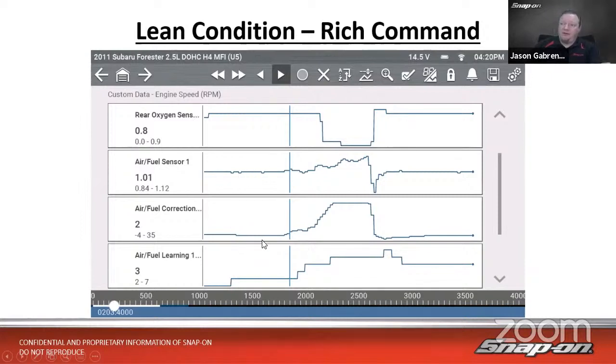So here we are right at the very beginning of the vacuum leak. We see it's fairly stable leading up to it, with very, very few changes in the signal. Rear's pretty flat. This is at idle, by the way. And then we see we're at like a 3% long-term fuel trim. All right, so as we open it up, we see that the fuel trim goes up. This is the front short-term fuel trim. We see the AF sensors going up slowly as well.